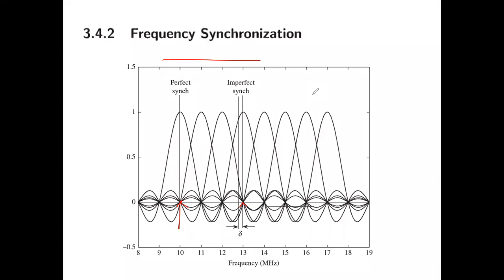Doppler effect, and because of that, your carrier, the center single carrier, is now shifted. Once the carrier shifts, all these subcarriers also slightly dwindle. And when that happens, the magical way it works is that whenever you are sampling this particular peak here, all other contributions from all the neighboring ones are actually zero.